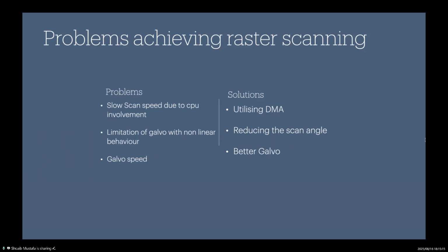I think what we achieved with this was, without the DMA, we had like 100 hertz or 200 hertz of conversion speed for drawing the pixels, and when we used the DMA, we achieved a speed of around 1 kilohertz. So that was a pretty significant bump, and it also helped us try to look into the future uses of it.